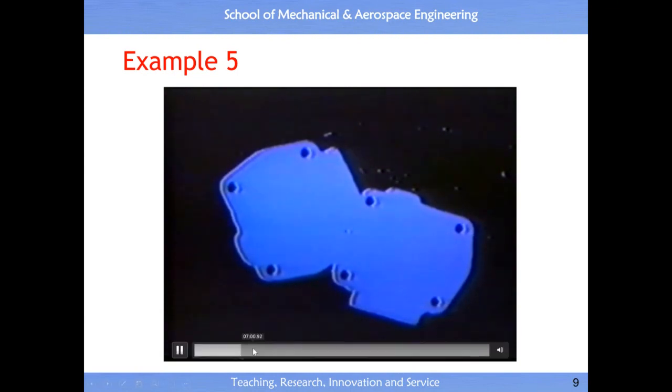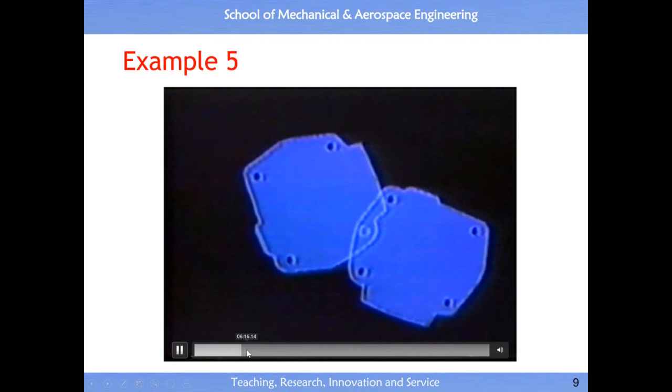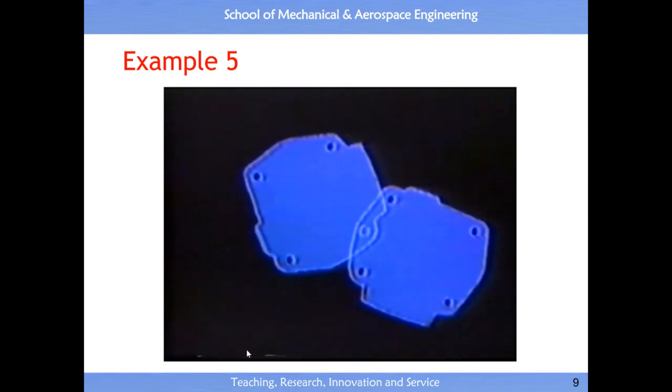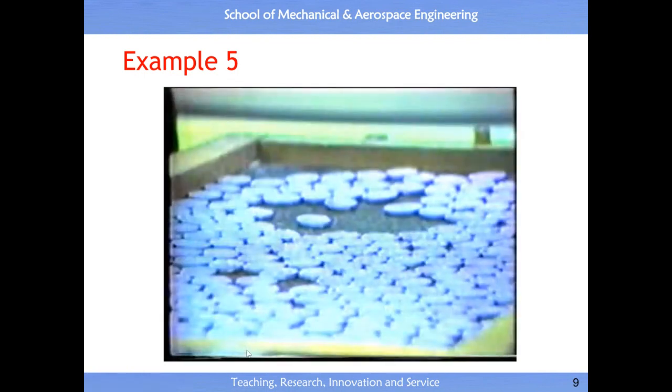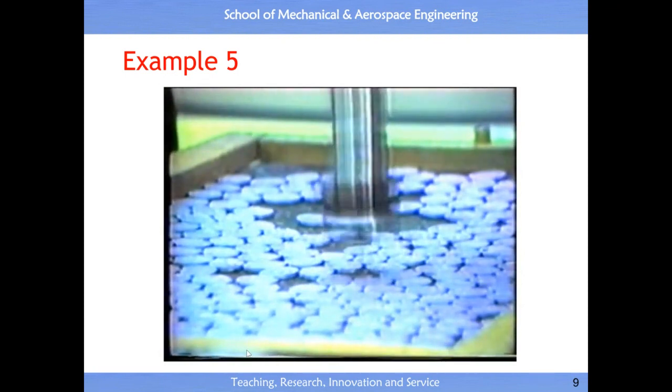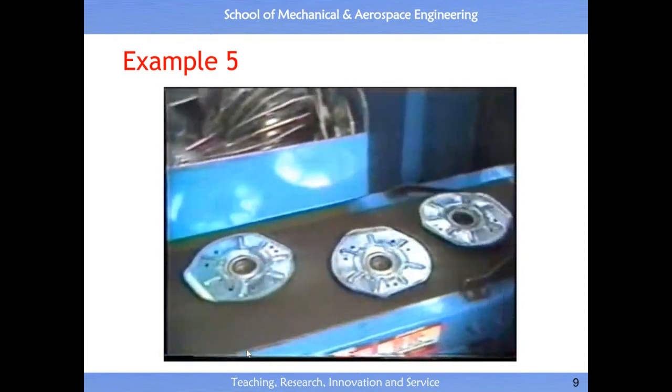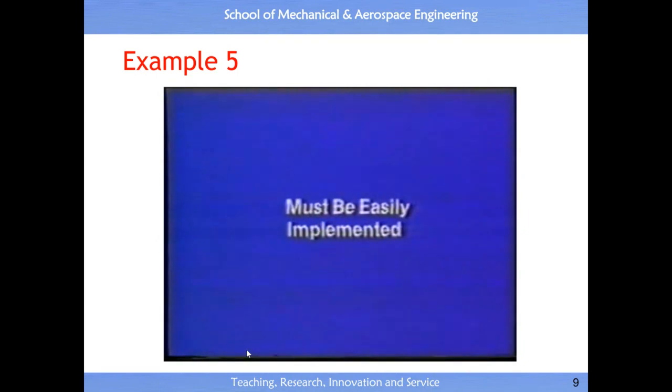Because as long as enough features are located, the system extrapolates the rest of the image and identifies the parts. This means you can present parts loosely and at any orientation in simple trays or on conveyors. Finally, robot guidance vision must be easy to install and train.